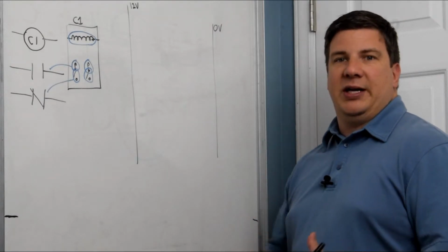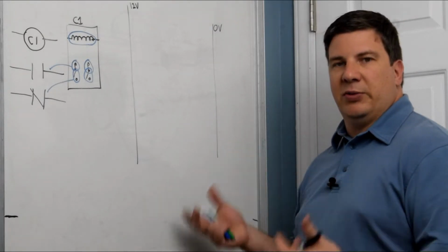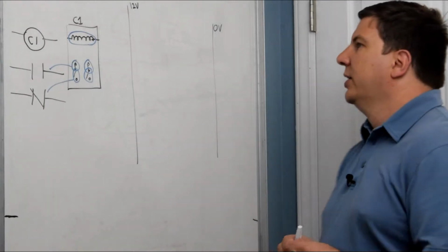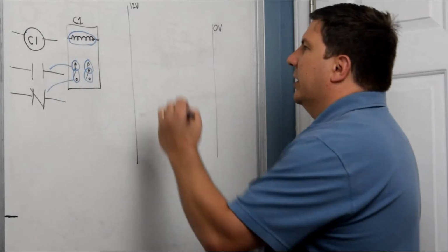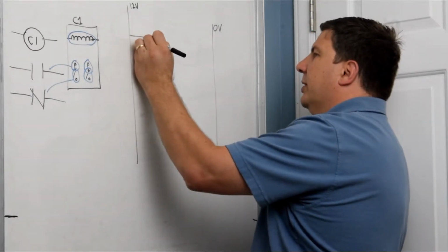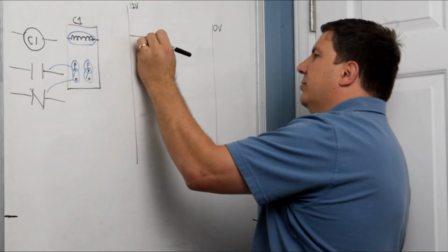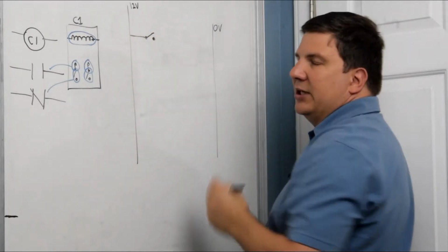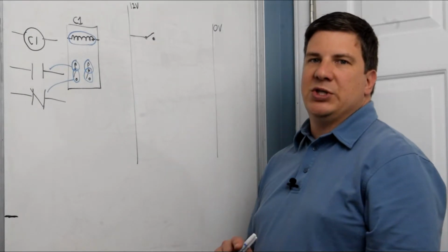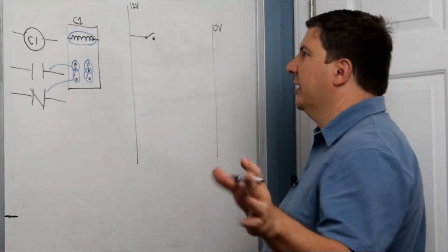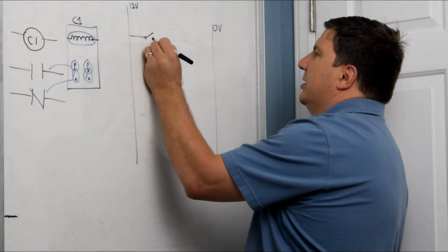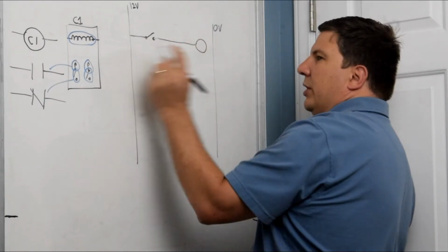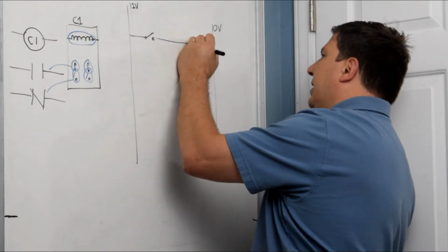We were having a headlight switch turn on a relay, and then that relay contact would turn on the actual light. Okay, so first thing we're going to do is we're going to run it up to the operator. We're going to have his switch, and you can represent these as many things. There's pressure switches, push button switches, limit switches. They all have different representations, and we will have a link to that. And then we're going to put our circle here and our contact 1.